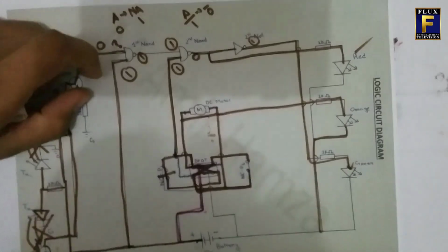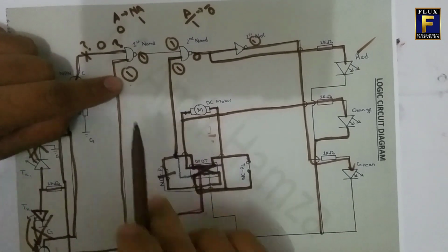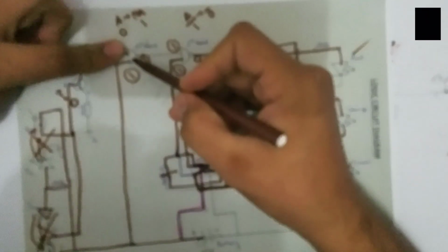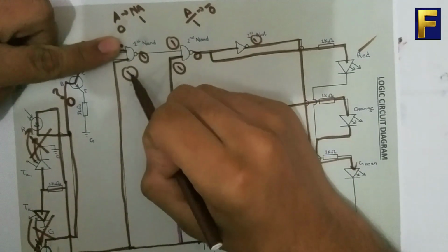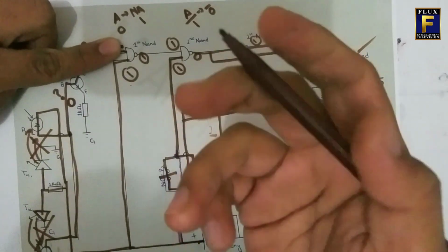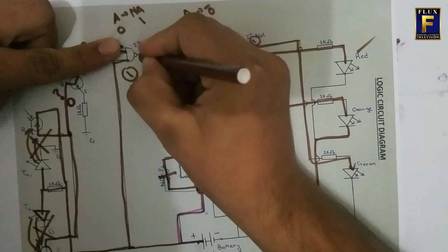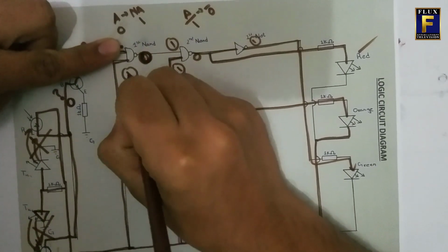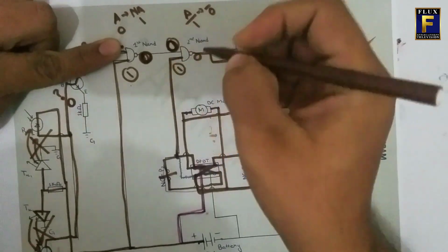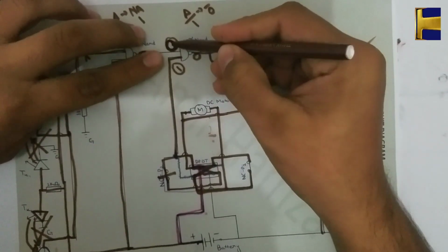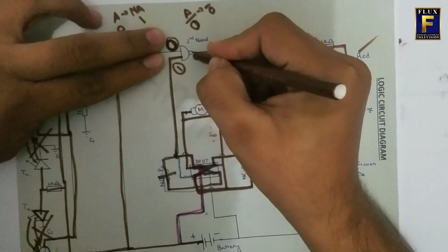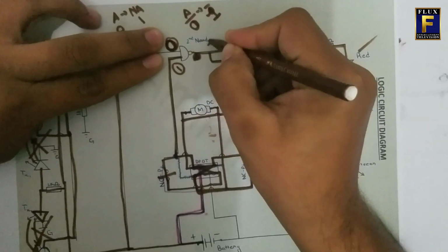Now here comes the work of that interconnection. Now what will happen? It has no NAND gate input. It will start working directly as a NOT gate and convert 1 into 0. So we start getting 0 here, because 1 is there. From NOT we get 0, and when we get 0 here, what will happen? 1 and 0 in the AND gate is 0, and when it passes through the NOT it will be 1, so we again start getting 1 here.